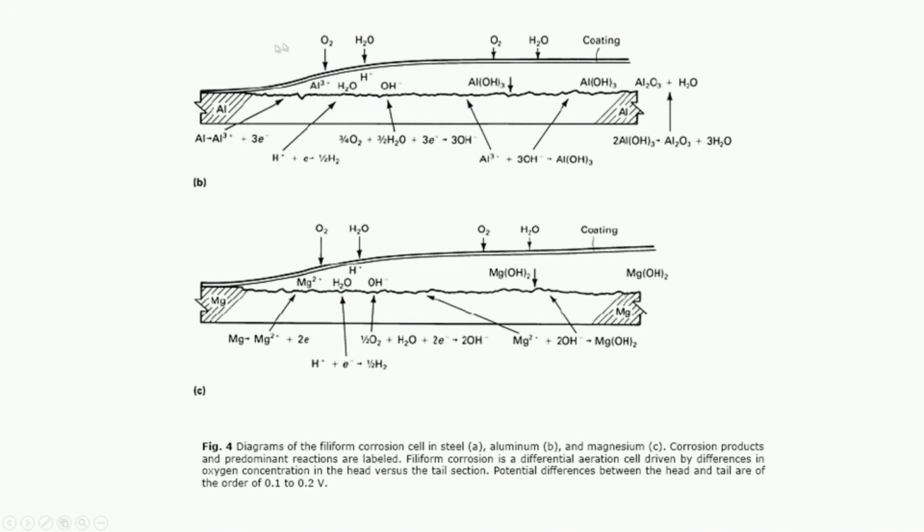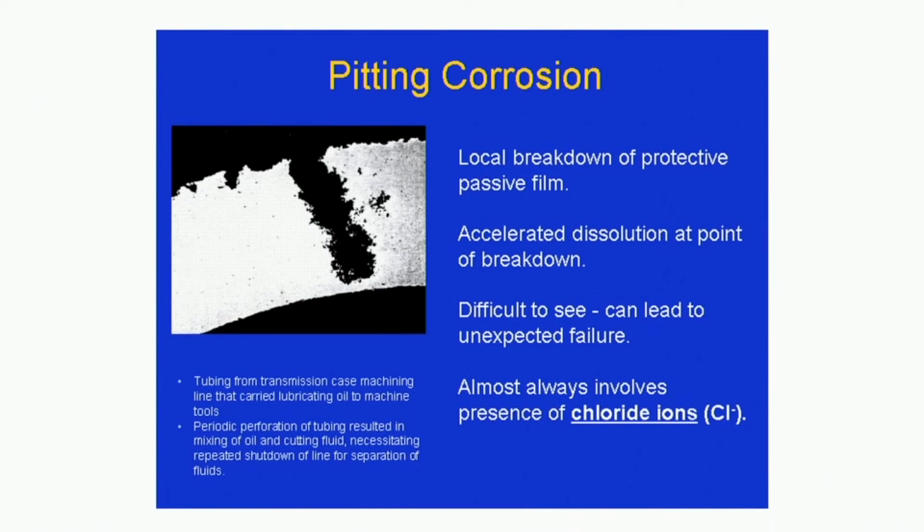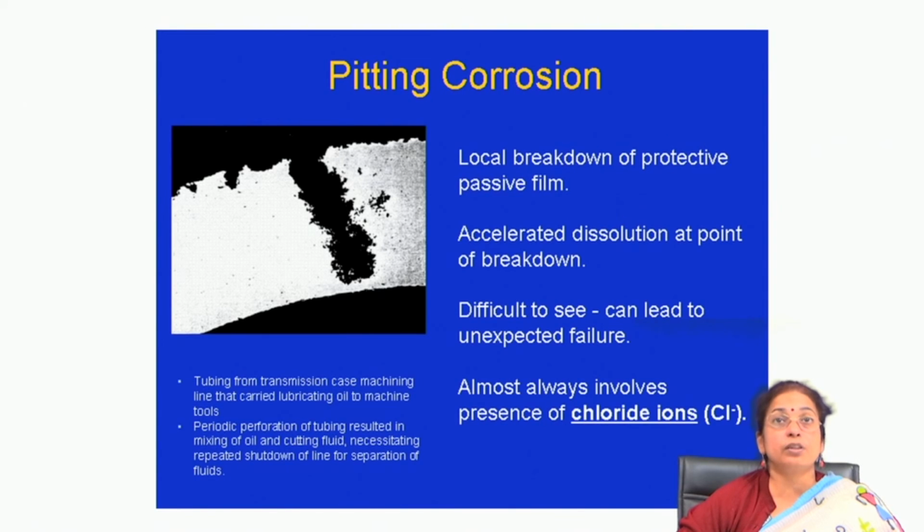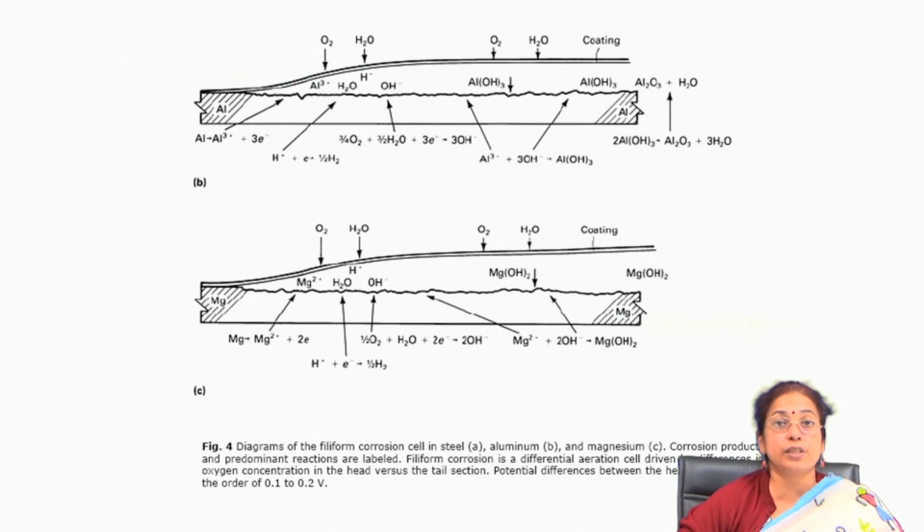This is usually observed in aluminum, magnesium and iron surfaces, whose hydroxides are very prone to get hydrated or absorb moisture, and which are very prone to corrode in an aqueous environment. Another important type of corrosion is pitting corrosion.